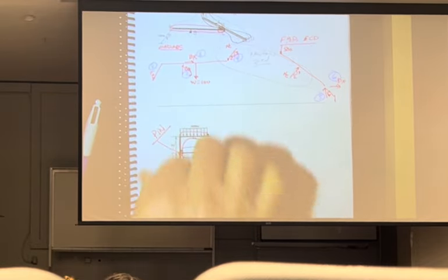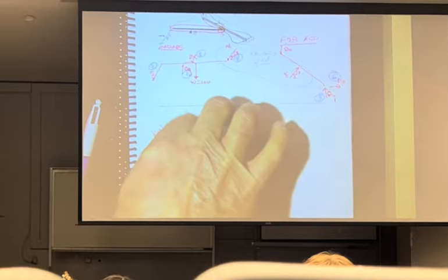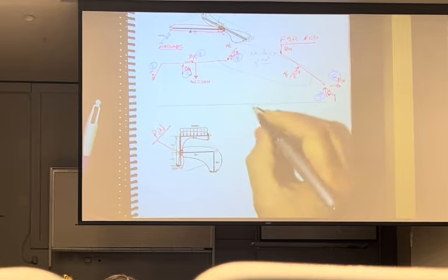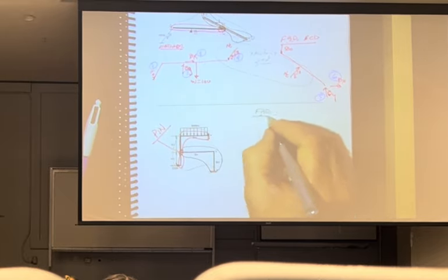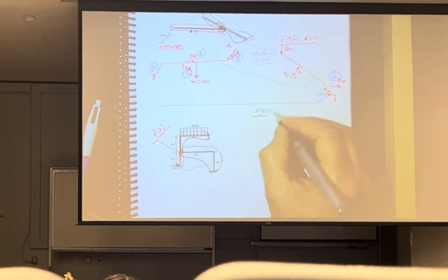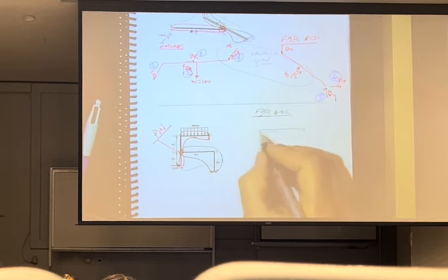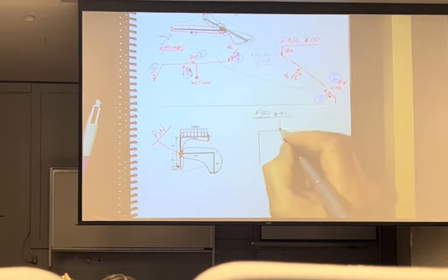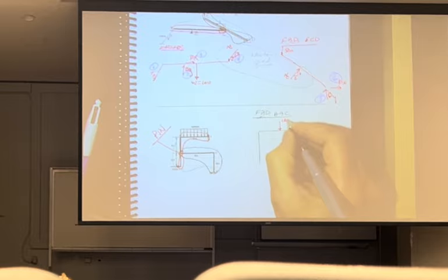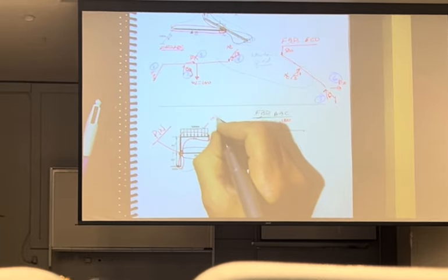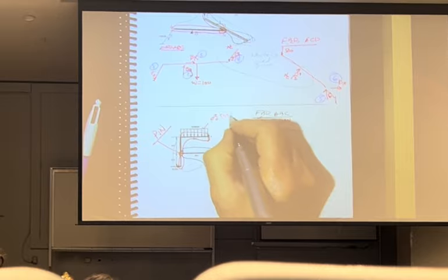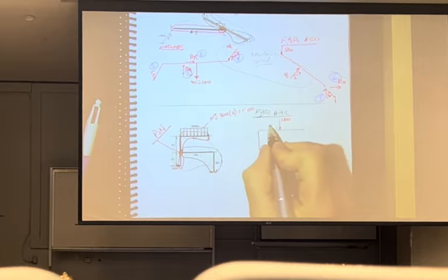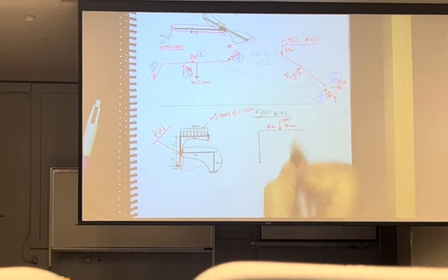So literally what I'm doing is I'm taking this pin, squeezing it, pulling it out, and then separating the 2 pieces. So I'll have a free body diagram of ABC, which is this guy, in which case I will have a single force resultant from the distributed load of 1800. 300 times 6, that's 1800. Half of 6 is 3 meters, so we'll put 3 meters here, 3 meters there.